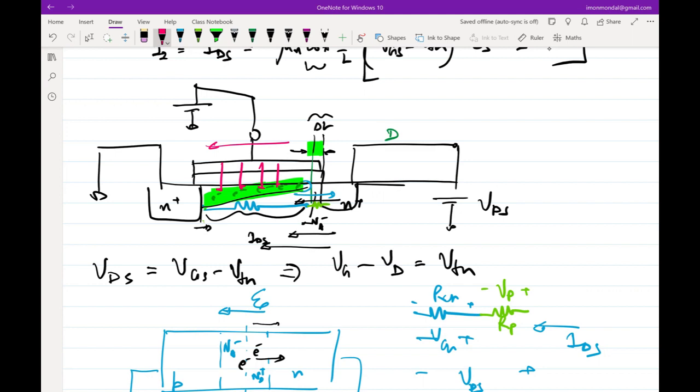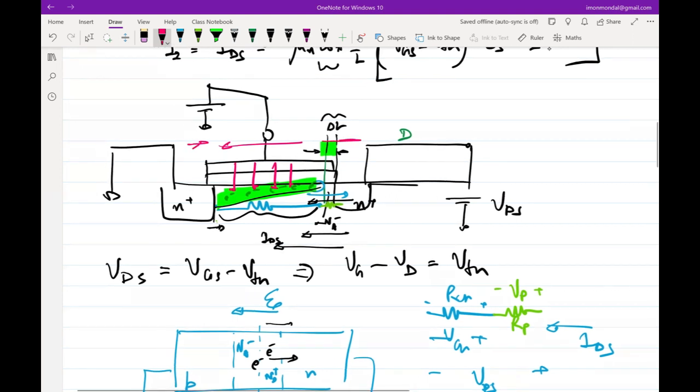So very often this VDS or the VGS max that you can apply is determined by the breakdown condition of that particular MOSFET. And you should be able to appreciate this because these numbers are often touted in the news, that TSMC is making 3 nanometer MOSFETs, 3 nanometer node, 16 nanometer node, and so on. That number, 3 nanometer, 16 nanometer, or whatever, refers to the length of the channel. So this L refers to the technology node. When you say 3 nanometer, that L is 3 nanometer. When you say 65 nanometer, that L is 65 nanometer.